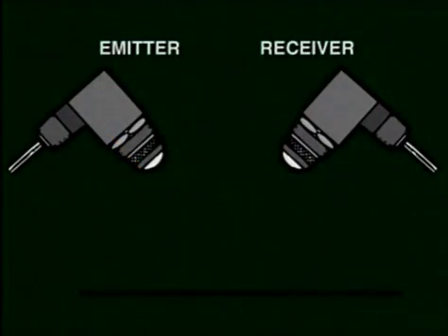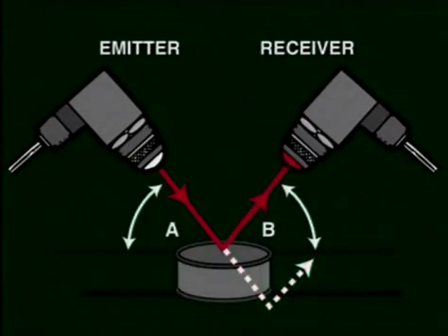The specular scan sends a beam to a shiny surface, which reflects it to a receiver, which is placed at an angle. Note that the positioning of the source and the receiver becomes critical and must be precise. When the beam is broken or reflected, as in this case, then the switch is activated.